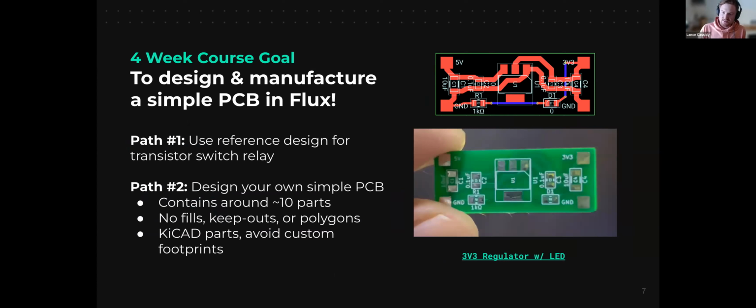So it's going to be pretty simple, but we can handle, basically, I think up to 8-layer boards. And then the fourth session, we're going to talk about ordering, sourcing, assembly, checking for manufacturability, how to do your Gerber export, working with manufacturers, and then we're going to assemble the PCB using a little setup rig that Jarwin has there.